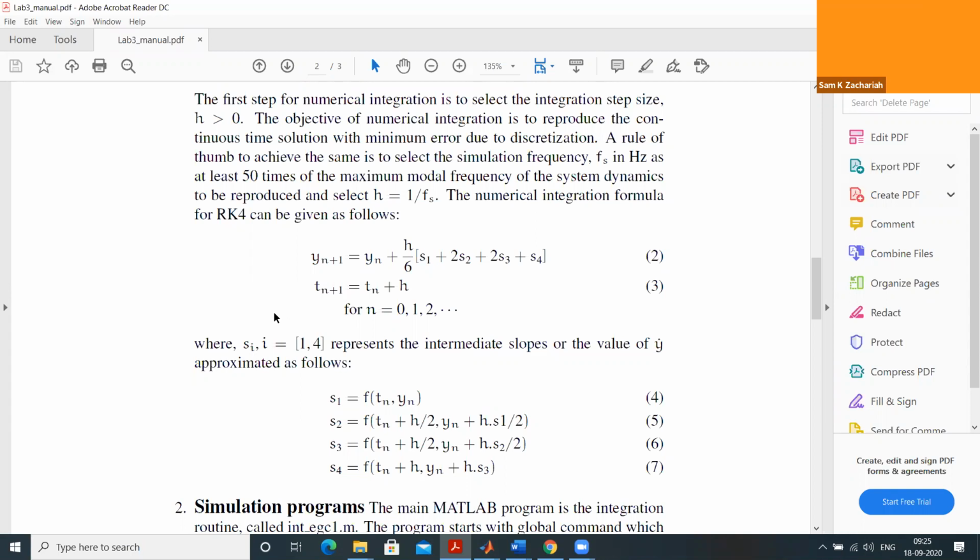That means the digital autopilot is giving a command to the engine gimbal control system to oscillate the engine at 5 hertz with, say, 0.4 degree amplitude. The control system should do it. That is, the output deflection should track the command. But exactly, nobody can track. There will be an attenuation with respect to amplitude, and a phase lag with respect to the phase.